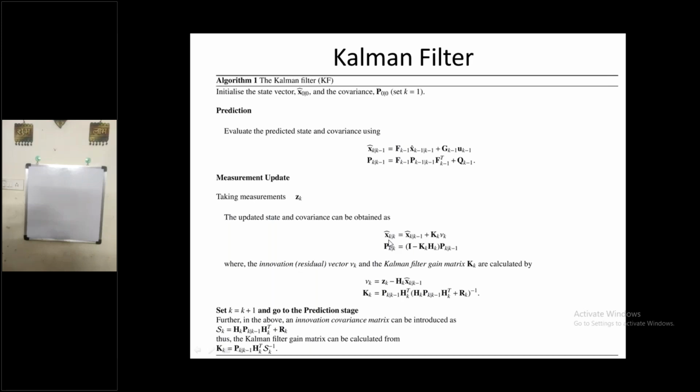If I say x10, it will have the information about all of x1, x2, x3 up to x9. So you don't have to go back to x1 through x9, and you don't have to keep that information saved. That is the very good advantage of this Kalman filter. Only the previous step is enough; the previous step value is enough to calculate the future one.